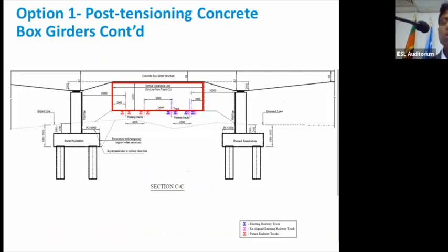Then, as you see, here is another picture of that. The red one is the clear boundary, the railway requirements, vertical and horizontal. As you see, it's not a perfect curve, but I will come back to it because there were tight constraints on the height. Otherwise, you need to raise the profile, which has another economic disadvantage. It needs land acquisitions, and it could have so many repercussions. So we have to deal with this available height that we were given, right?